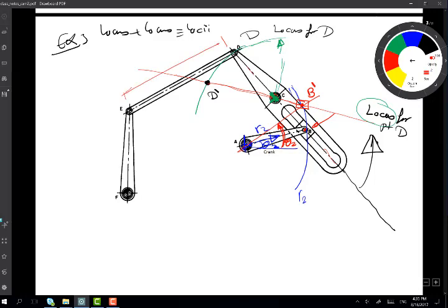and this tells me that point E moves on a circular arc whose center is D, right? So I can apply this immediately and draw a circular arc here, and the radius of this one is ED, with the center at this point here. So this here is a locus. I'm using this word one more time, locus of E. So I need to find another locus of E.